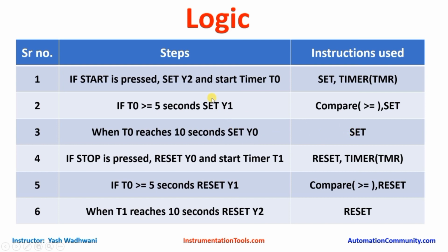feeding conveyor. Now friends, what I wanted is that my grinder should start 5 seconds after the starting of Y2, and my Y0 should start 5 seconds after the starting of Y1. So I have used one timer to turn on two outputs, Y1 and Y0.